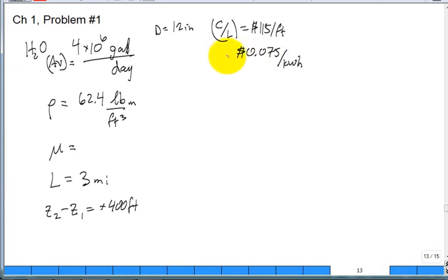How do we write that? Well, cost per the energy, maybe something like that. And you want this to go a lifetime of 15 years. You only bury the pipe once, buy it and install it once, and that's the cost to put it in the ground once. But then every year, you're going to have to provide electricity to run the pump, to push the water, overcome the friction and bring it up the elevation, true? To overcome both the friction and the elevation. So the efficiency of the pump is 56%.